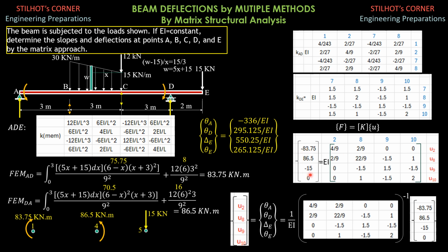So these are the nodal forces. Factor of EI, which is common. Then we have 2, 2, 2, 2, you add 4 over 9 only. Then 2, row 2, column 8, 2, 8. So we have 2 over 9. Then 2, 9, there's no 29 there, 0. 210, there's no 210 there, so 0. Then we just copy because the matrix is symmetric. So we can just copy 2 over 9, 0, 0.